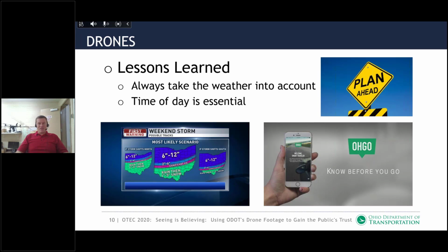Some things to consider are nearby school arrival and dismissal times, as well as restaurants around lunch hour, and of course the beginning and the end of a workday. Typically, we're trying to record intersections when the traffic volume is highest, and pinpointing these times helps us be more effective with our mission planning and execution. I have to admit, I've been late to a flight location or two because I've mistimed the traffic peak and ended up stuck in the traffic I was trying to record.